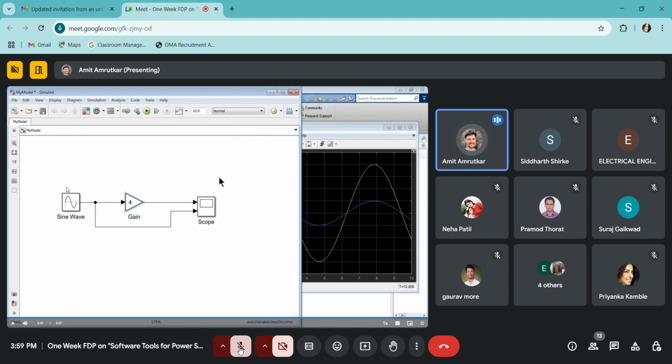So this is the power of MATLAB or Simulink. Again, you can configure all readily available blocks and just double click and set the value whatever is required. And while tuning any PID or parameter or device, you have to implement in such a way that you can easily modify your function parameters.